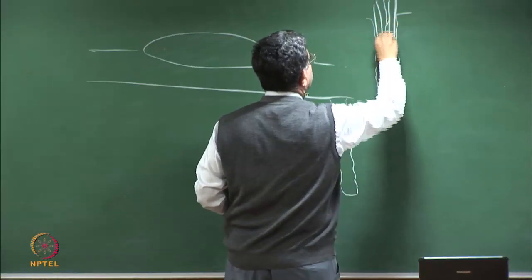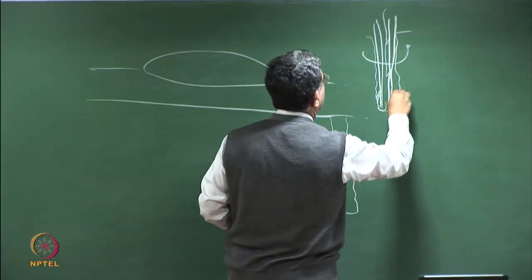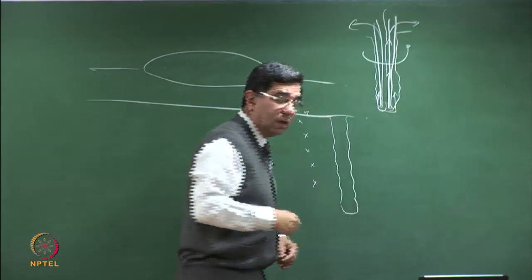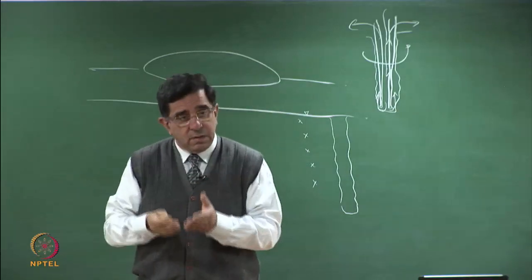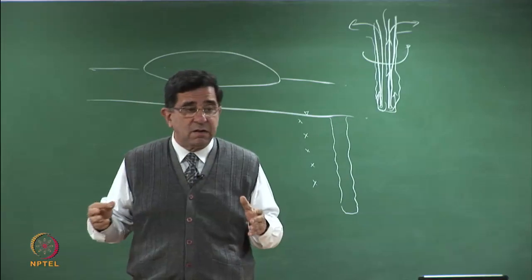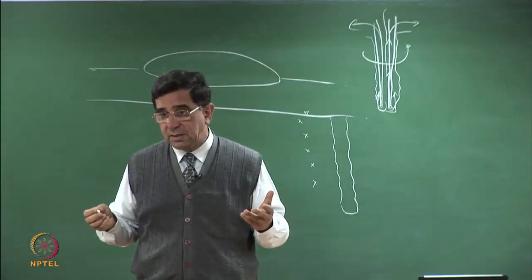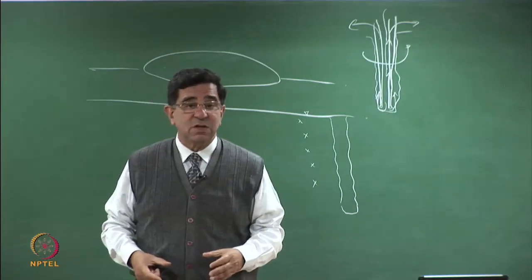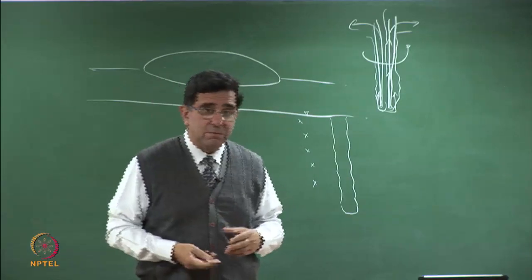Your fluids are coming in, this casing is rotating, and the cuttings are coming out. It keeps on cutting; you don't take out the casing, suppose you have to go very deep. The slurry coming from the annular space between the casing and the borehole carries out the material which has been cut. Once you have reached a particular level, then you put in your pipe with the screens and remove your casing. And in the annular space, you fill up the gravel.